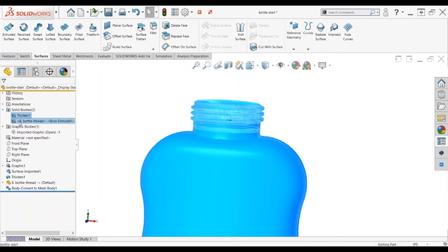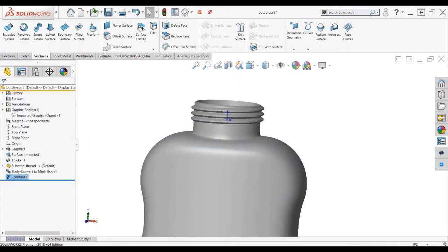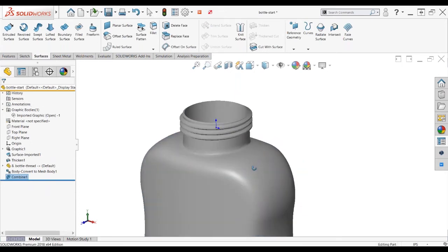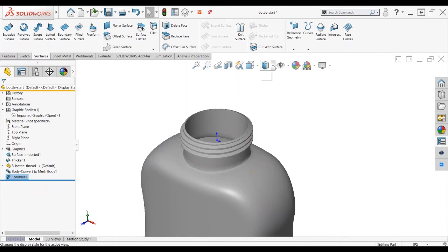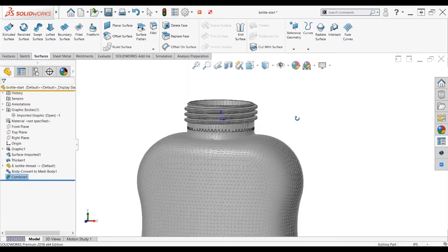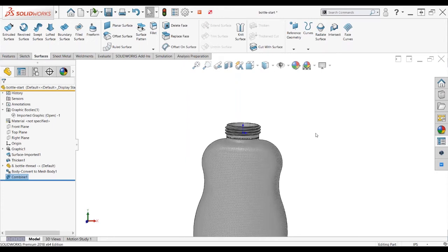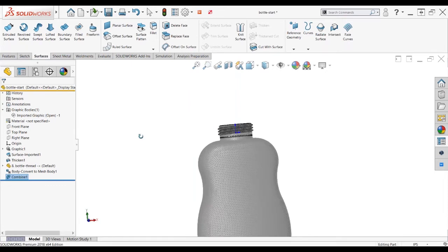And since they're of the same type, I can now combine them with my Boolean operations. So I'm just going to add them together. And now I have one single solid body, which is an STL. It has all of my little triangular tessellations. So I can now save this as an STL and get that printed out on a printer really, really easily. And most importantly, do the modifications really easily.